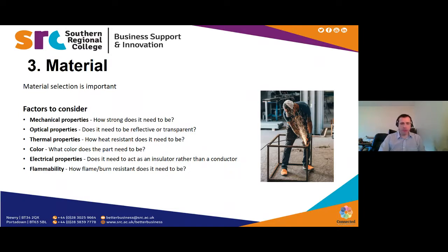For example, having nice curvatures or nice plastic parts. Of course, you could probably manufacture them, but the mold might cost 10,000, 50,000, and that might be outside the cost of actually producing the part. So although it may be a really nice design, there might be a conflict and compromises might have to be achieved. And it's trying to balance that, and I think understanding this early and talking about it early means that these critical decisions can be made early.